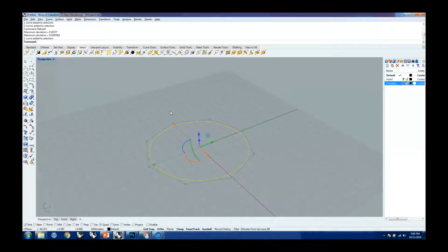So when I loft the whole thing, there is some drama on the surface and it's not very regular. Okay, so let's just select. I'm just selecting diametrically opposite points and then scaling them, which still keeps it sort of symmetrical. But now let's see, I'm just going to make some changes here and there.